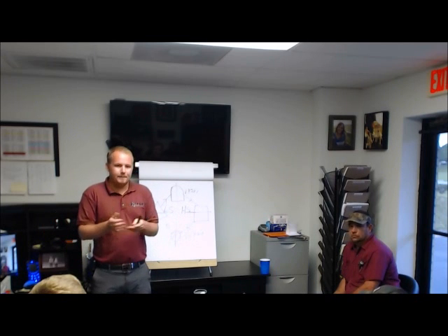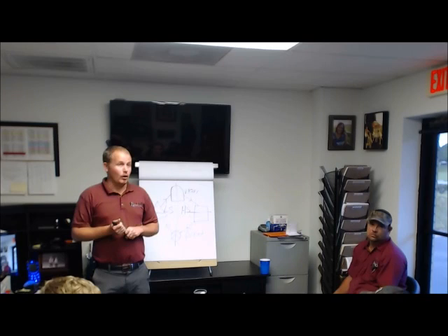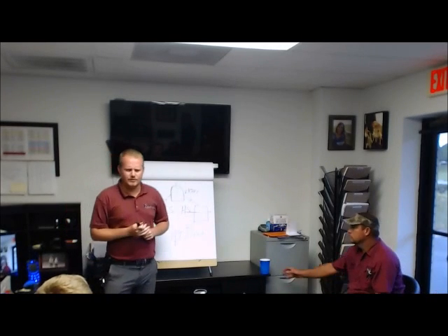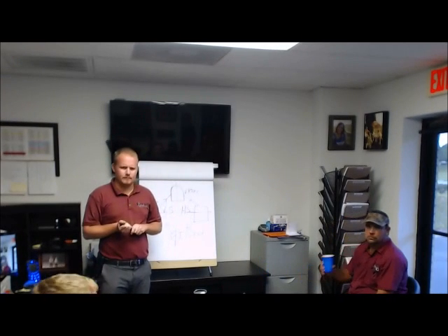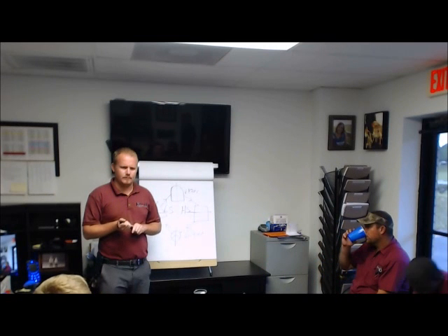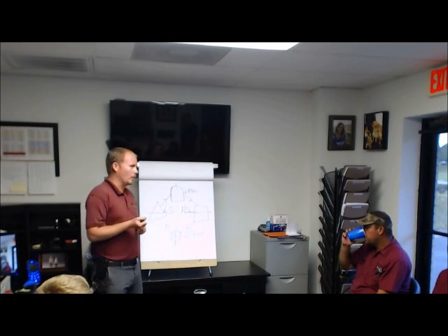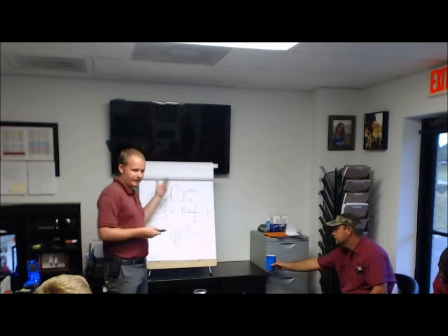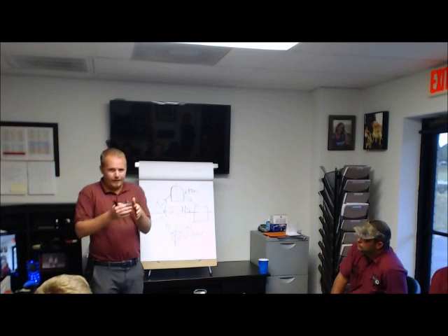Meaning that, I'm sorry? Then you're gonna saturate the condenser. Well, it's its own... What do you mean? Look, I'm trying to do vapor, and you're gonna saturate the evap. What you're saying is you're going to overfeed the evaporator coil as well. Yeah, right. There's other things that factor in there.